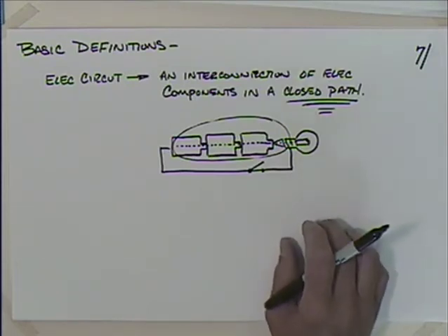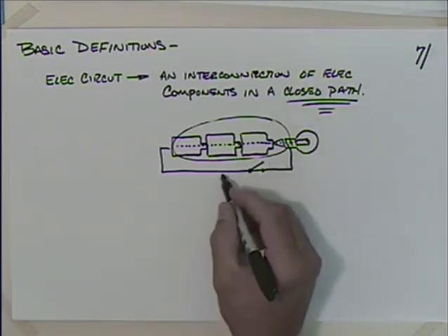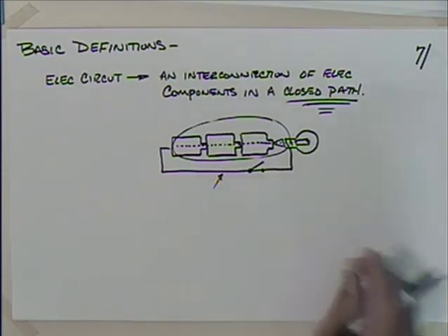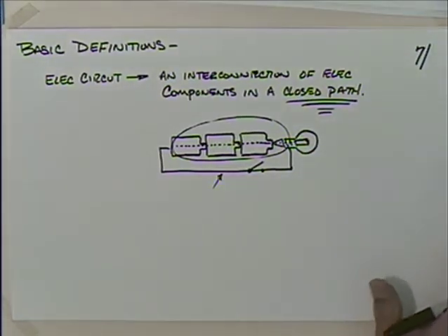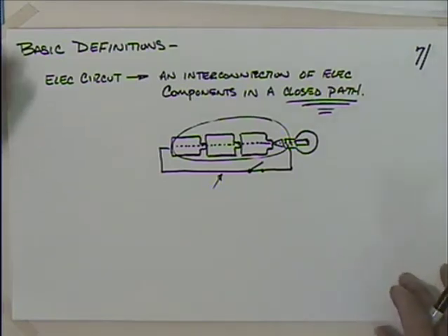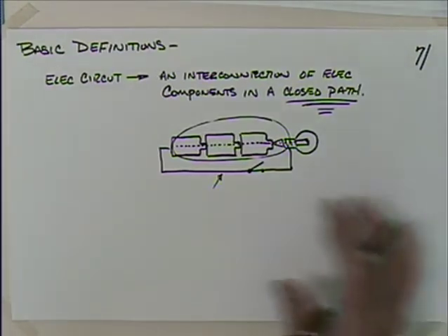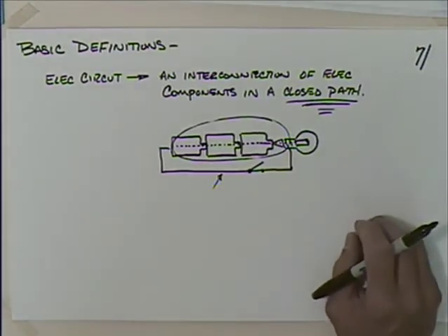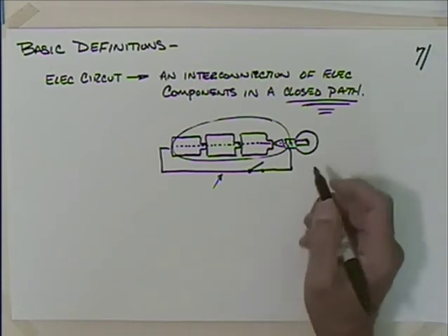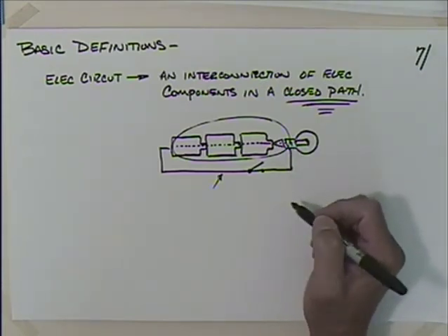So sometimes this path is a little hard to find. If you have a metal body flashlight, you may not necessarily see that. They're probably using the body of the flashlight itself for that. If you have a marker light in the fender of your car, you pull it out and it probably just has one wire going to it if it's just a single marker light. And you might wonder, well, is that some weird phenomena they're using? Well, no, they're using the fender, the metal fender, the chassis itself, as this return path.